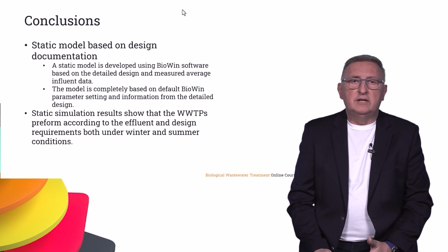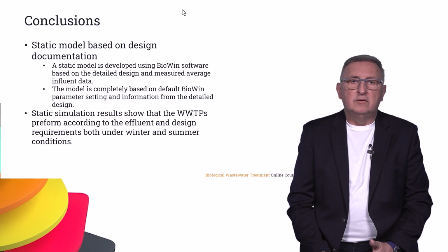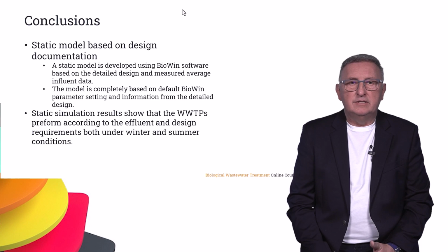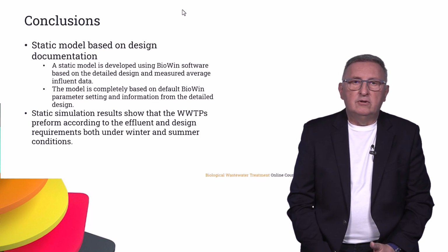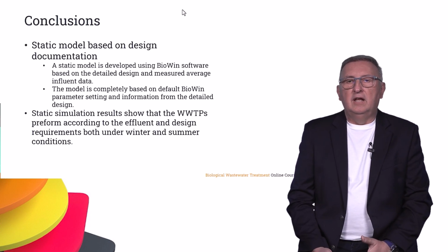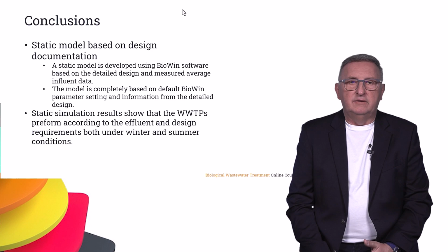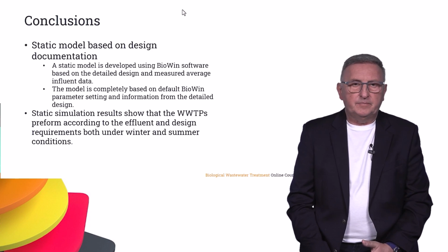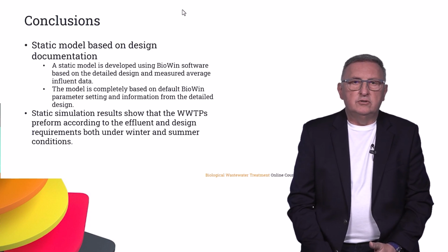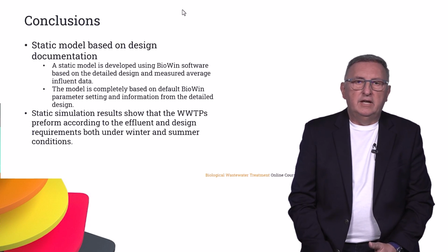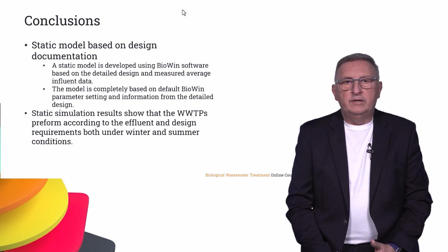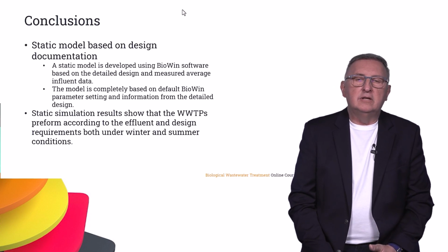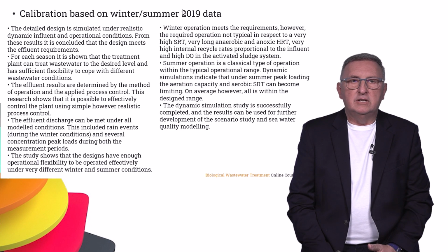That model was really using detailed design of the consultant and measured average influent data from sampling campaigns. The model is completely based on the default BioWin parameter settings and information from detailed design. So in this particular case, we did not change any of the default parameters of the model. Static simulation also showed that the wastewater treatment plant performed according to the effluent and design requirements for both winter and summer conditions. And that was a very important conclusion of this first part of the modeling study.